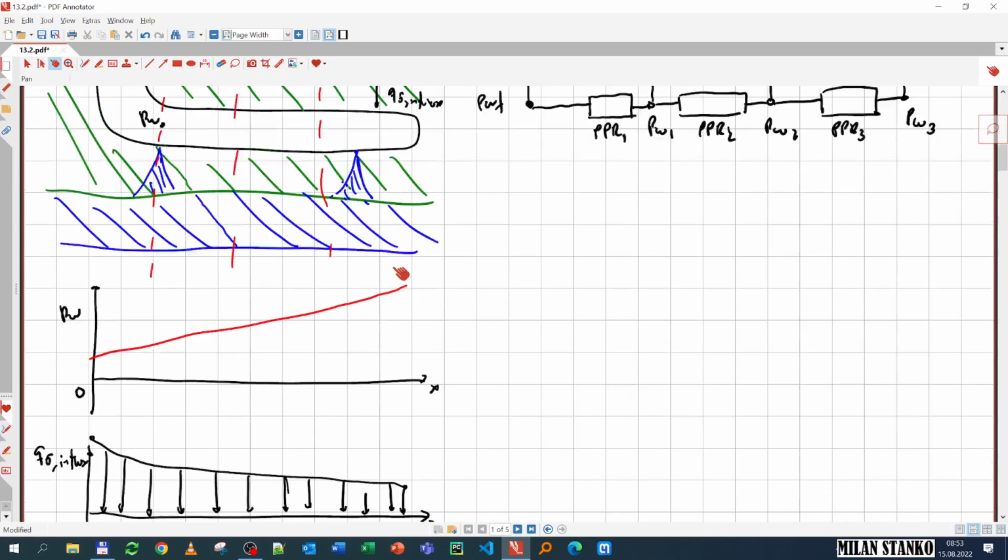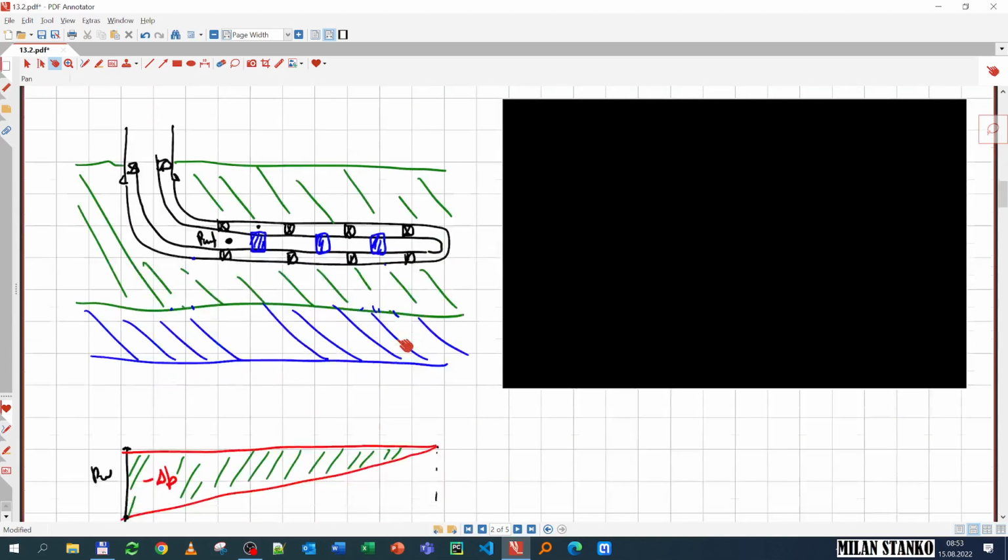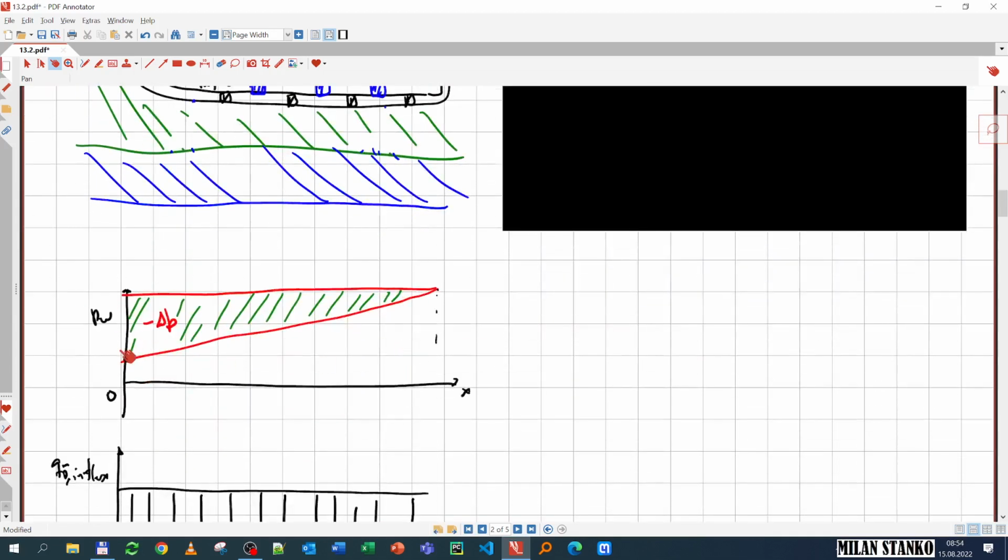It will be ideal if I can lower the pressure at the toe down to the same level as the heel, but then I will need to use some sort of a pump to reduce that pressure. The easiest is simply to increase the pressure at the heel, and for that I have to create an additional pressure drop to put everything together.